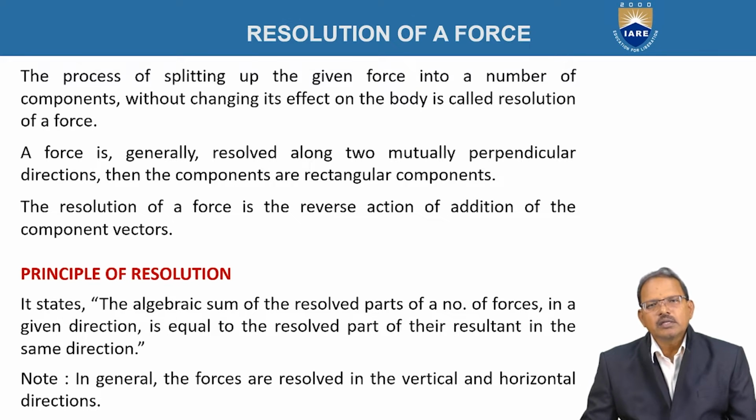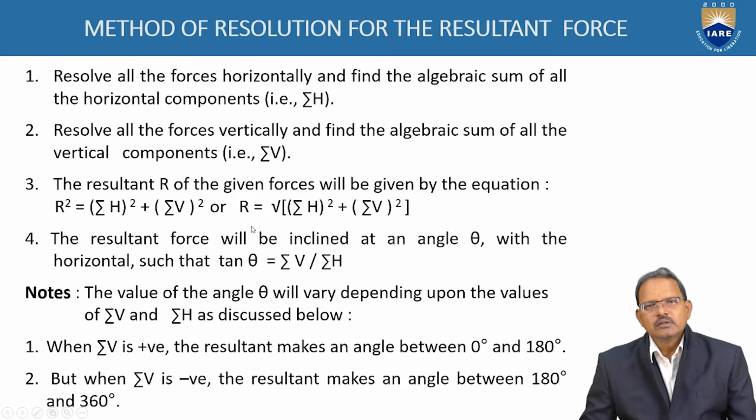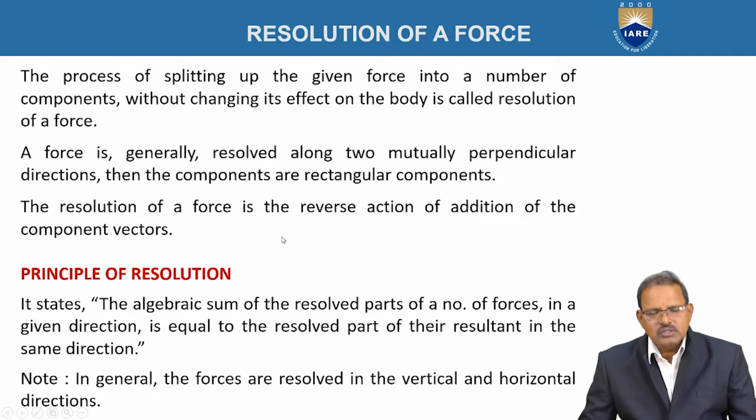But if the inclination between the two components is equal to 90 degrees, the components are called rectangular components. Generally, the force is resolved into rectangular components to find the resultant of the forces. The resolution of force is generally treated as the reverse process of addition of forces.